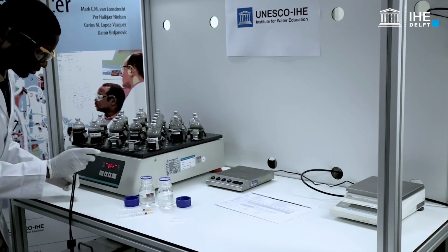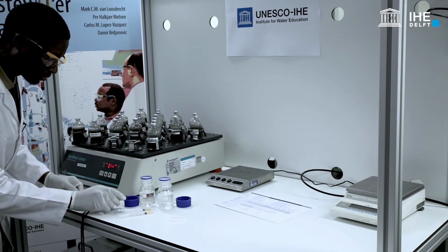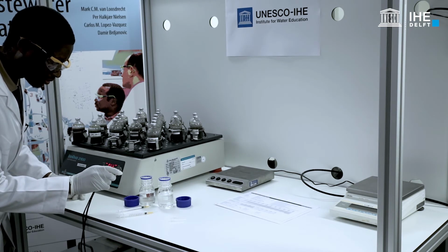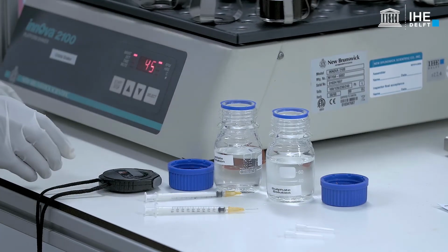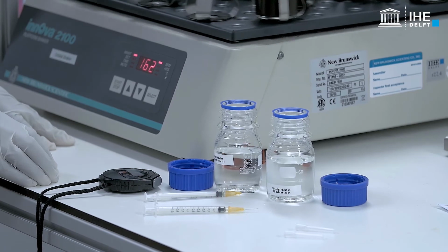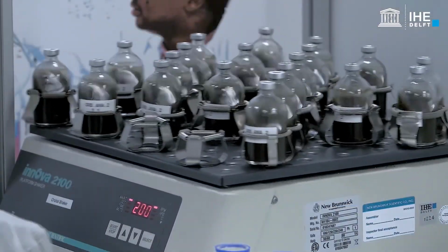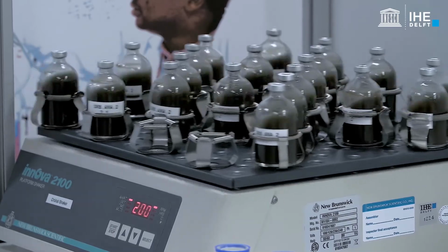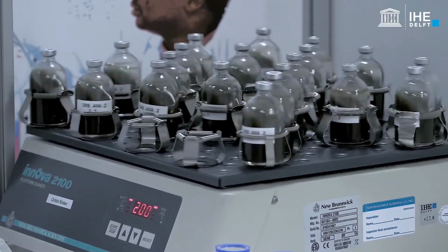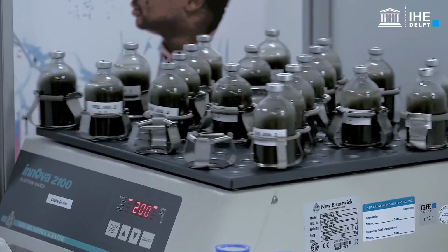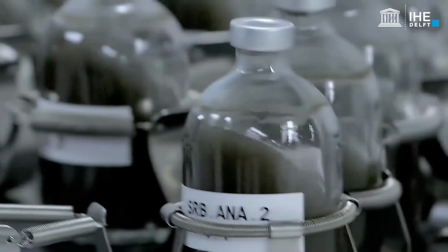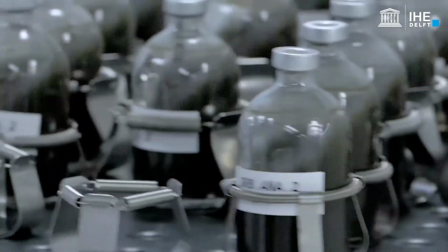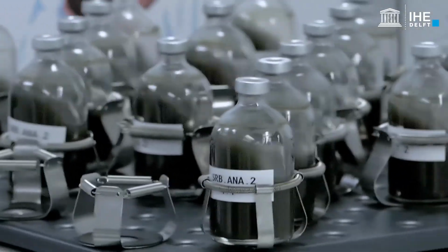Once all the solutions have been added to all the bottles, start the stopwatch to monitor the time. Start the orbital shaker and incubate the bottles. Continue with the collection of gas and liquid samples according to the design of the experiment.